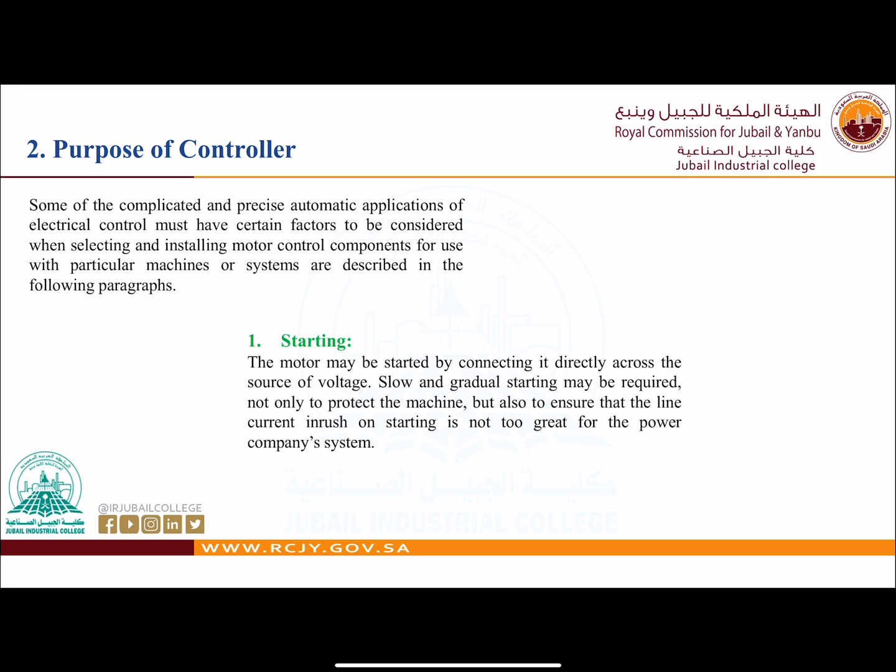So we know from the practical sessions that starting is very critical for a motor. So we need to gradually increase the voltage to overcome the problem with the inrush current, with the starting current. Okay, that's why we need controlling starting of the motor. Okay, and it is a very important factor.